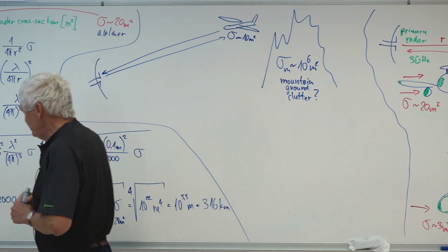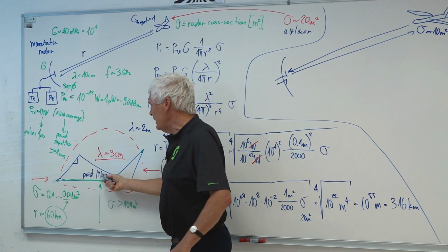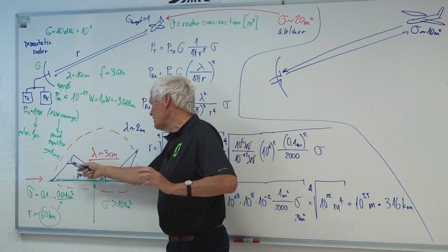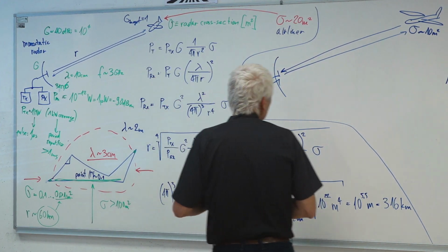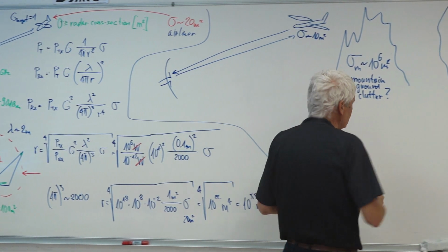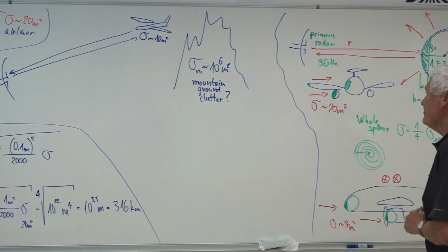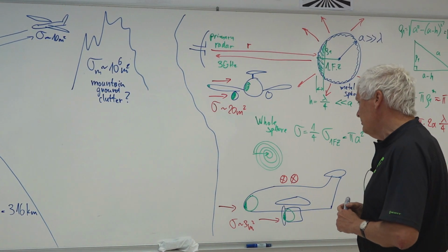It's easy. It's very easy when shooting at an aircraft from below. There are no mountains up in space, so the only reflection you have is of the aircraft. But in the real environment of civilian air traffic, you have this problem. How to solve this problem? You solve this problem with the Doppler shift.